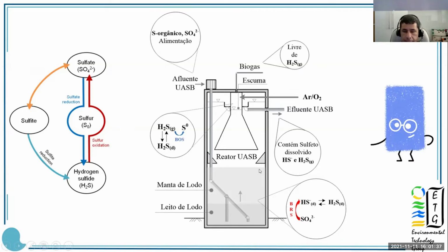As for how we apply microaerobic treatment, we assess different ways of microaeration, not only in the headspace, but for instance, for pharmaceuticals and micropollutants, the application of microaeration in the liquid phase has been shown to be more interesting and efficient to remove these compounds from the wastewater.